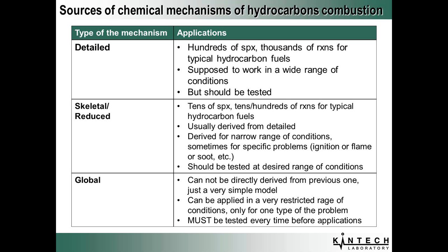Usually these mechanisms are derived from the detailed one, and when they are derived, it is supposed that they should work for a narrow range of conditions and for specific problems. For example, ignition simulations or flame simulation or prediction of some type of pollution, for example, NOx or unburned hydrocarbons or soot.